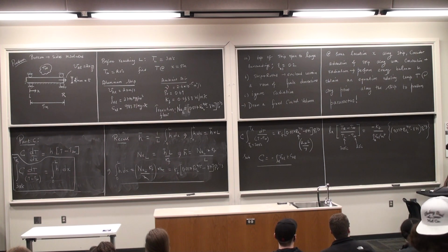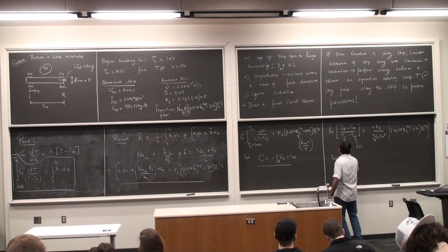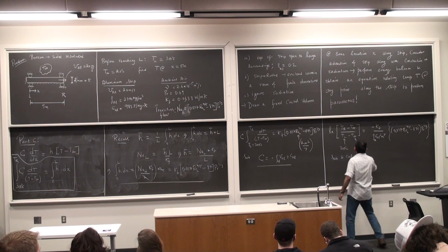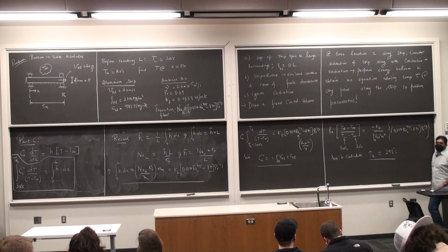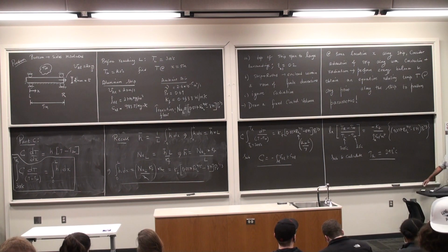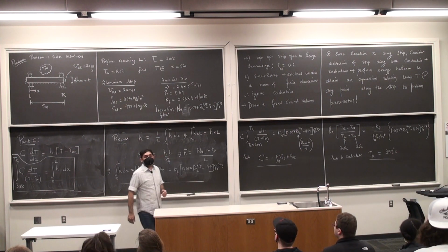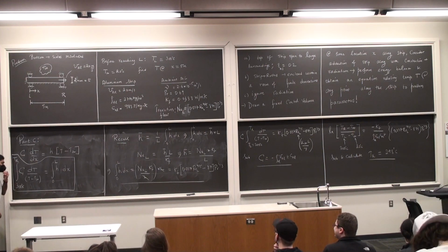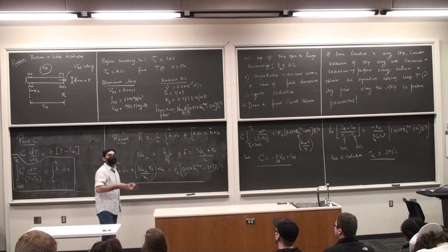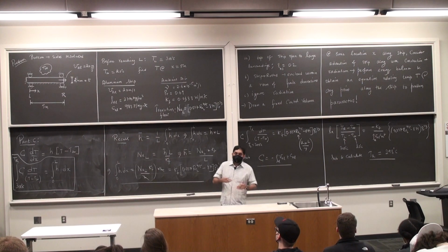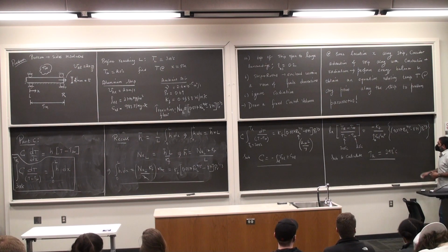ME 2850. Calculate TR. Ends up being 298 degrees Celsius. This is absolute disaster. I started at 300. I spent all this damn money. It's 298 degrees Celsius. This is atrocious design. Okay? So what should you do? Increase the velocity of the strip, so that your heat transfer coefficient increases. If the heat transfer coefficient increases, then your rate of heat transfer also increases. Convection heat transfer. Okay? So this is poor design.